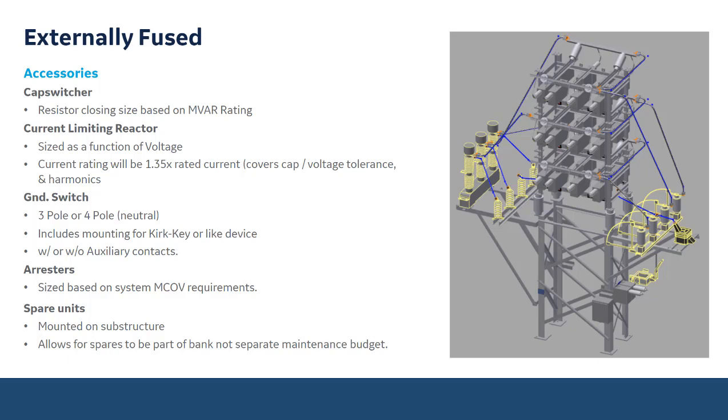And when designing for the arrester, you want the arrester to be as close to the equipment that you want to protect as possible. So in this example here, we see the arresters are right next to your phase connections and your neutral. That's where it's going to provide the best protection during the event of a lightning strike.